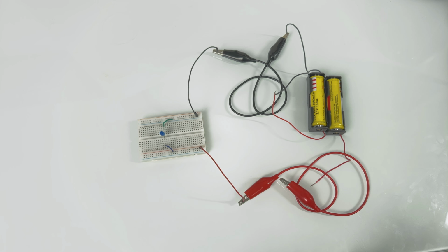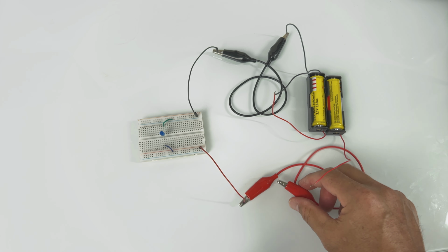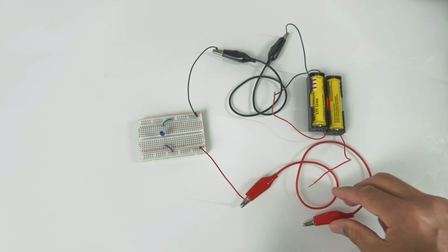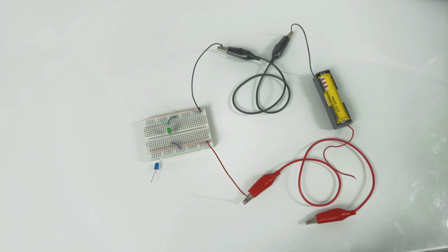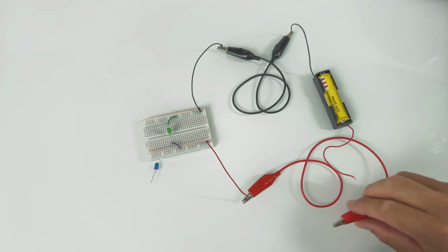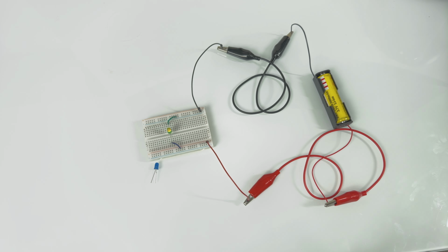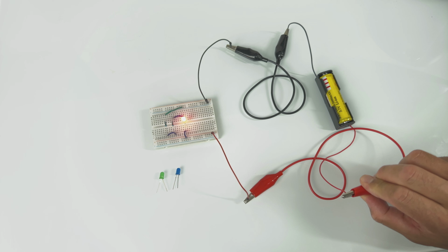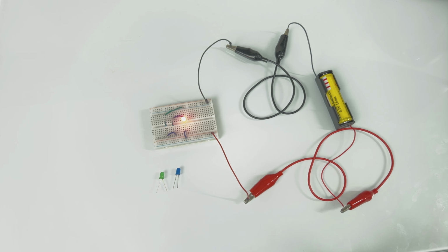One reason it's important to understand circuit properties is to avoid damage. In this first scenario, the blue LED burns out instantly because there's no resistor to limit the current. So without understanding circuit properties, too much current flows, destroying the LED. In the second scenario, this is a green LED and it burns out slowly. The resistor is too small, or in this case doesn't exist, allowing more current than the LED can handle over time. But there was less power, so it will burn slowly. In this third scenario, the LED stays lit because we use two resistors to bring the current to the correct level. Understanding circuit properties ensures the LED operates safely and reliably.